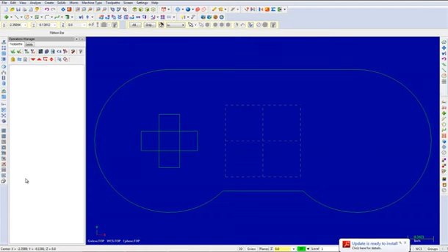We will now use the Trim Divide command. In this step, you will trim the entities using Divide, which trims a line, arc, or spline into two disjointed segments by removing the segment that lies between the two dividing intersections. When you choose the Divide Delete function and select an entity in the graphics window, Mastercam uses the nearest two intersections on each end to divide the entity. If only one intersection exists, the selected entity is trimmed to the single intersection. If no intersection is found on the selected entity, or the point of intersection is an endpoint of the selected entity, the entity is deleted.